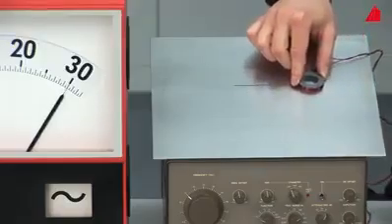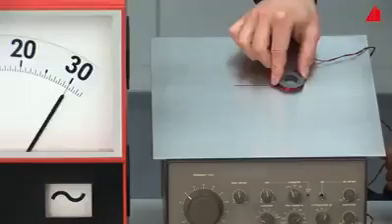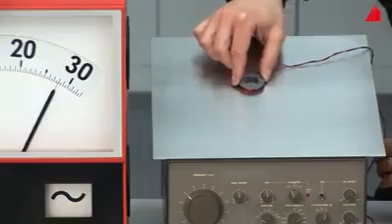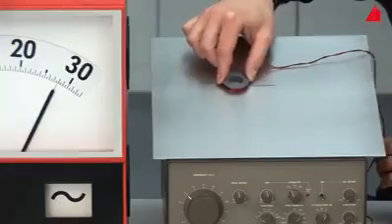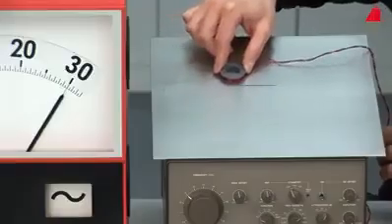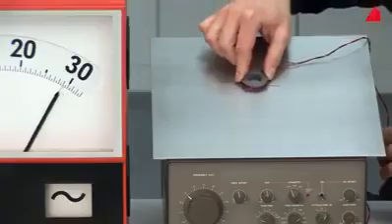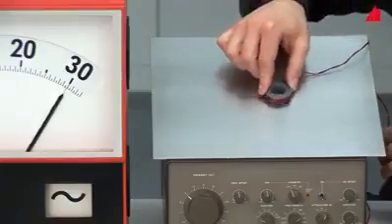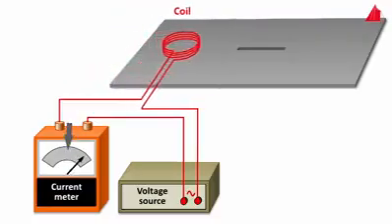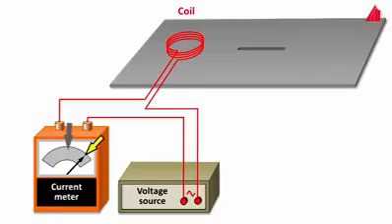In defect-free areas, the current consumption of the coil is high. In the area of the saw cut, the current drops noticeably and reaches its full height again in the intact area. The same effect can be observed when the coil is moved across the saw cut from top to bottom. The animation shows that the current consumption is low when the coil is still far away from the sheet. This is due to high self-induction. As soon as the coil is placed on the sheet surface, the current increases.